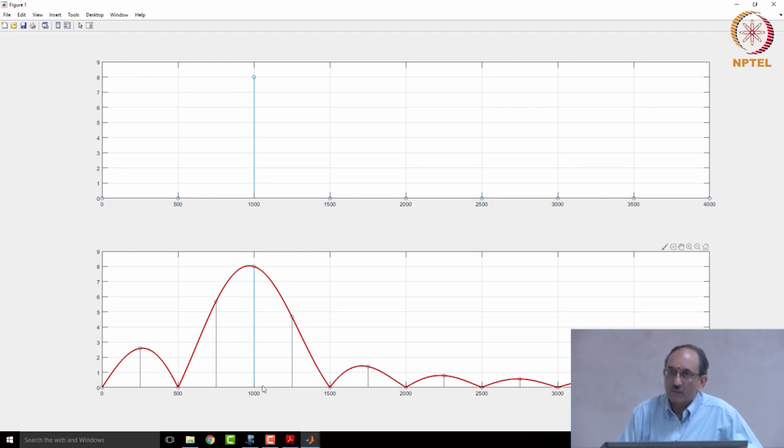very good DFT that has been heavily zero padded, and rather than using the stem plot, I am using the regular plot, and what the regular plot does is join consecutive points by straight lines. Therefore, this apparently smooth looking curve, if you really zoom in, will contain a set of straight lines connecting points that are closely spaced, that is all.